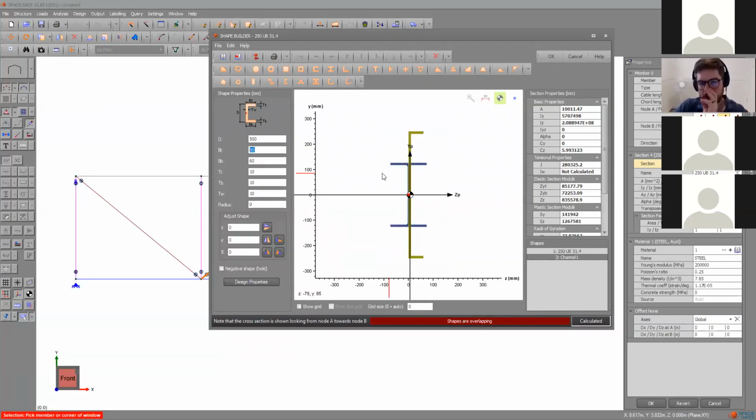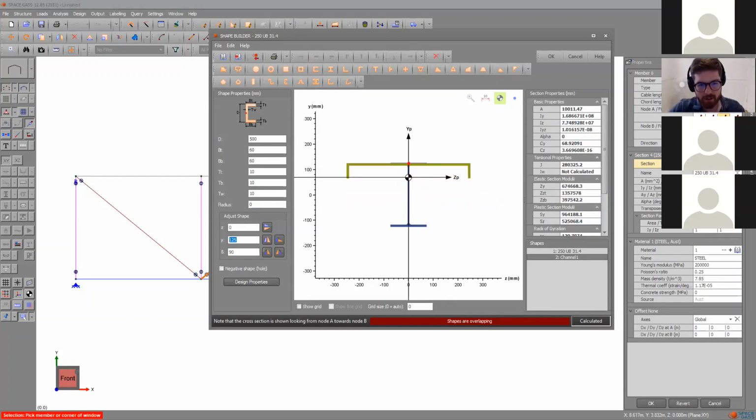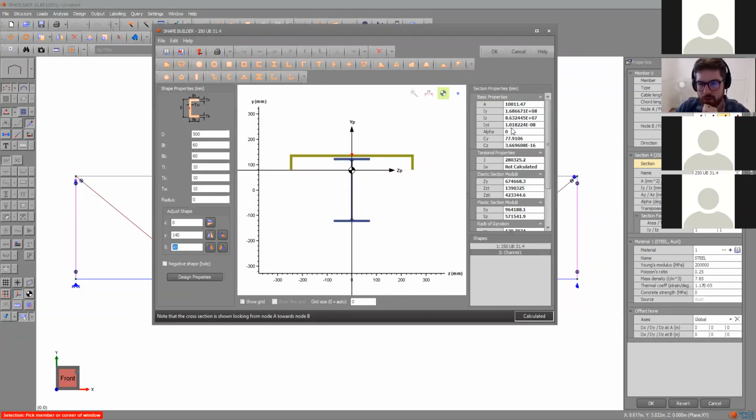So if you have a section that's composed, say, of two steel elements, here about Z, there, you can build your compound section by inputting it exactly. And in fact, if any of you are in your early years of your course, Civil 2330 particularly, you can use this information to check all the questions that you're getting on calculating section properties and so on and so forth. So it's a super useful tool.